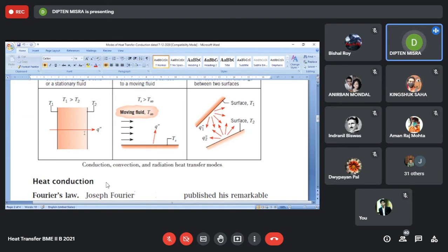So if we integrate the heat flux over the entire surface, we get the heat transfer rate from the entire surface. This integration may simply be equal to the heat flux multiplied by the surface area if the heat flux is uniform over the entire surface area. Then the heat transfer rate will simply be the product of the constant heat flux and the total surface area.